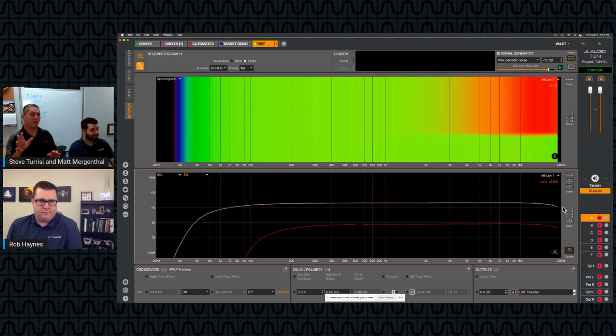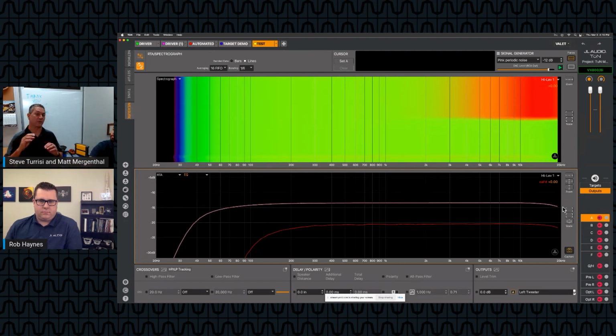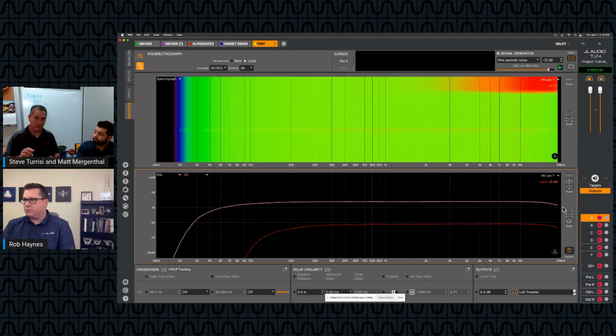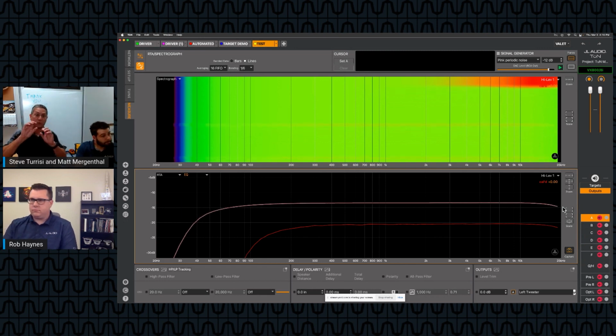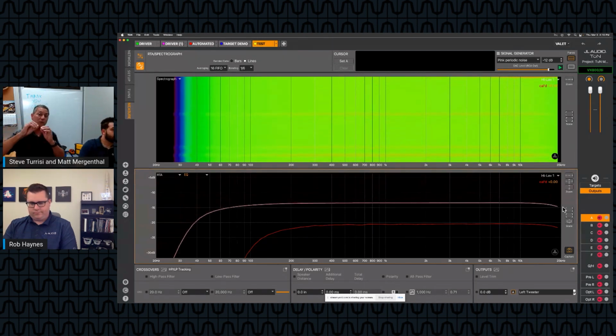And what's interesting about this with chimes is a lot of guys are probably thinking, well, I could probably see that on an RTA. Well, it depends on how fast your RTA is updating. If it's in a very rapid refresh rate, yes, you'll see the door chimes, but it'll be very hard to identify where that took place. So also, in those cases, your RTA is going to be moving a lot more as a more dynamic signal. So what you could do here is looking at the spectrograph, you'll see a burst of energy at whatever frequency that door chime was, and it'll pass in time. So you'll see how long it was, as well as what frequency it was. So you can actually see noise after it happened and not have to stare at your RTA. You can make the noise happen and then look at your screen.